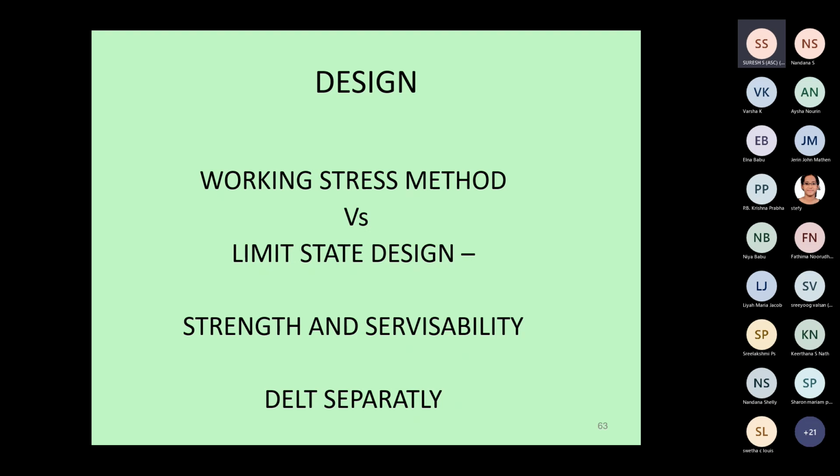Like if you have an excess deflection in a structure, people will find it difficult to stand on the structure or use the structure because it is deflecting. They may be afraid of moving in, thinking that it may fail. It may not fail. Strength part is all right. It can stand, but still the excess deflection will give the user a feeling that he is standing on an unsafe structure. So the deflection has to be controlled to the satisfaction of the user. So this is called serviceability. The structure should be not only strong enough, but it should be serviceable as well.